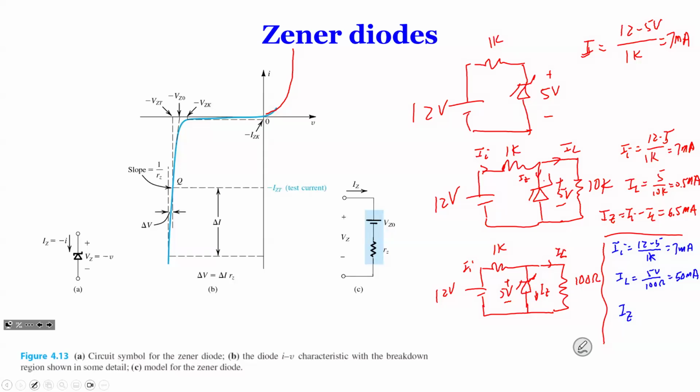And somebody may say, oh, you have a diode, can the current flow up there this way? Well, yeah, it can, but where would it supply it? So in this case, our calculation here is actually totally wrong because there will be no current flowing in the Zener diode, which means you will not be able to sustain the 5 volts.